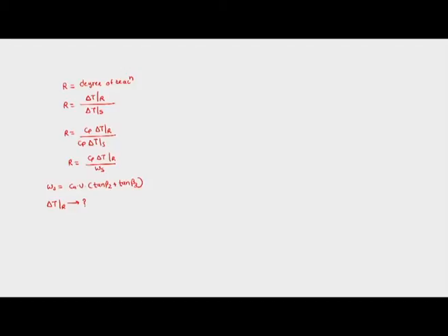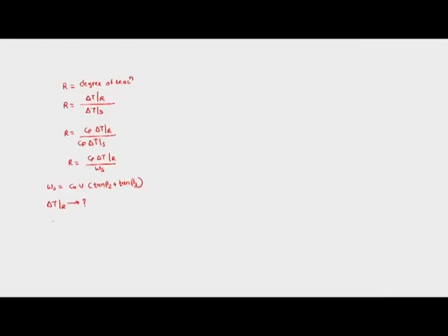So we can go to the velocity triangle, or from the TS diagram we know one point: the absolute total temperature doesn't change in the nozzle, similarly the relative total temperature doesn't change in the rotor. So relative total temperature means H2 plus V2 square by 2 is the same as H3 plus V3 square by 2.